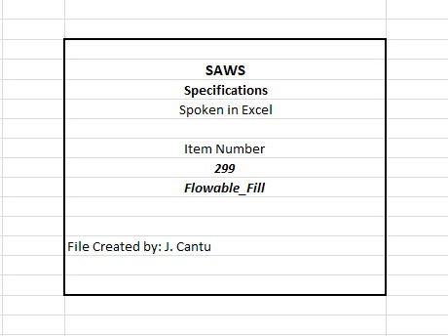299.4 Materials. 1. Cement. Furnish hydraulic cement that meets the requirements of TxDOT DMS 4600, Hydraulic Cement, TxDOT Hydraulic Cement Quality Monitoring Program, HCQMP, and ASTM C150 Type I Portland Cement.